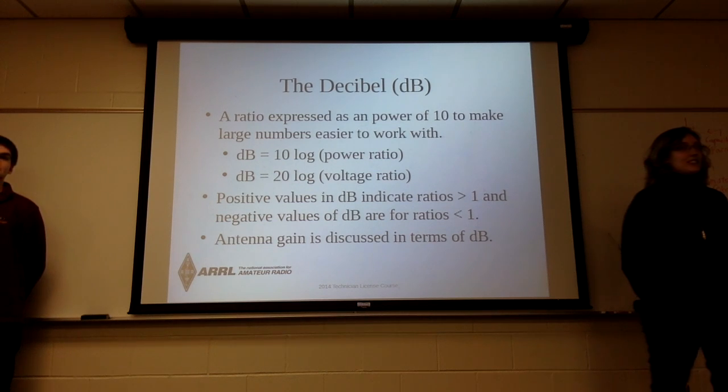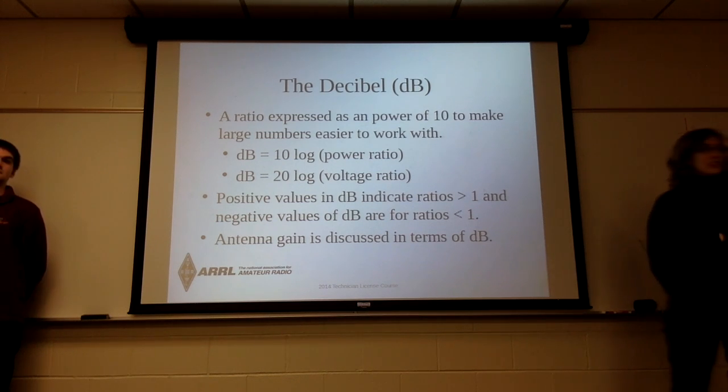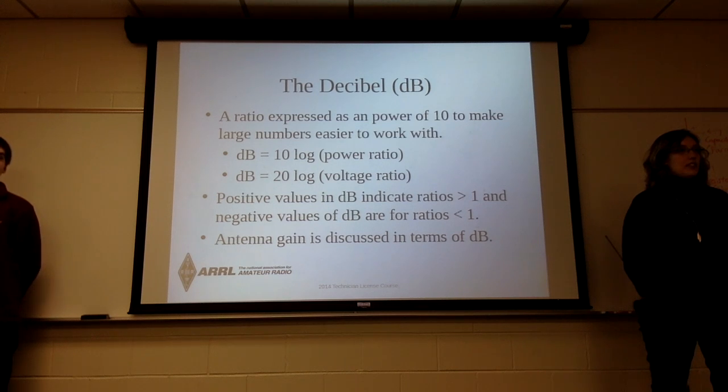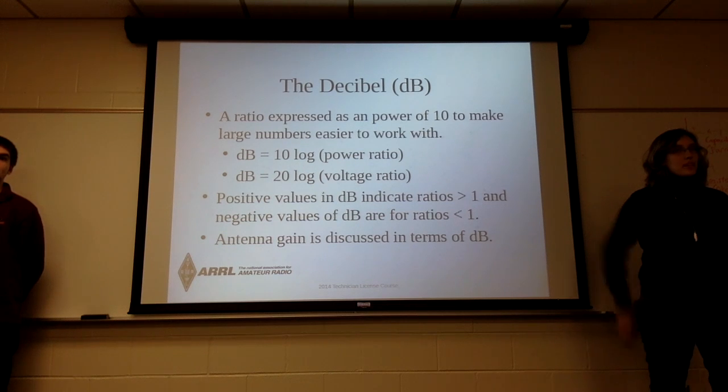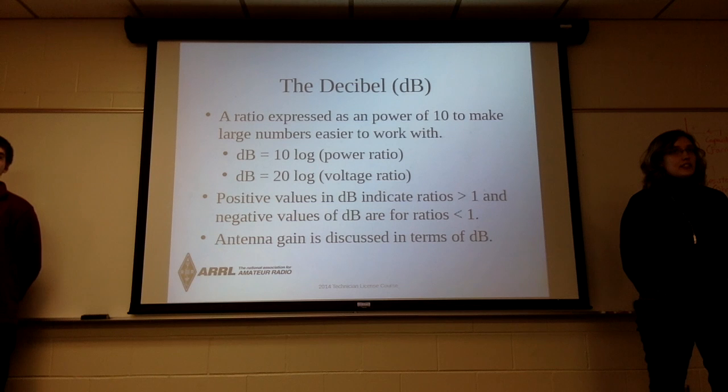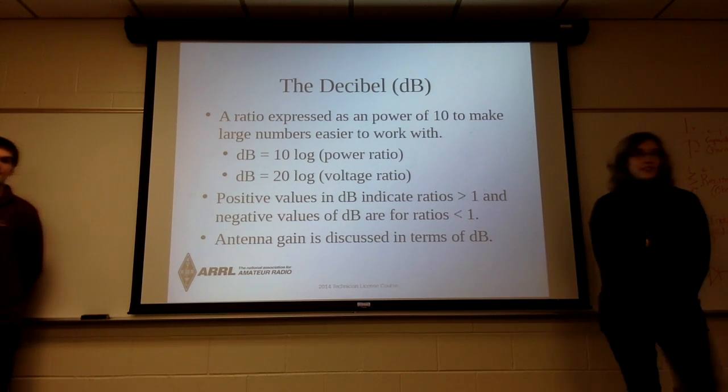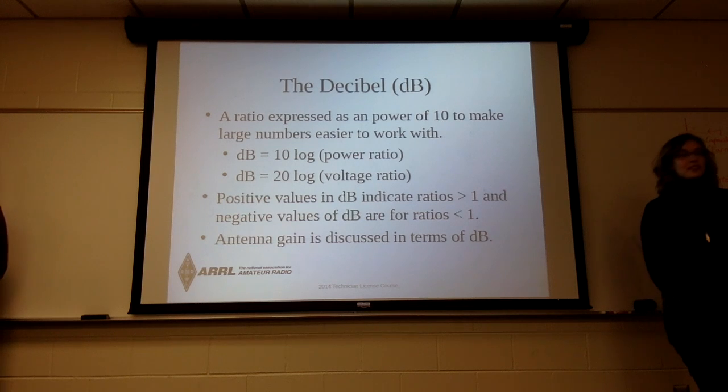Okay. Typically, mobile stations like me use vertical polarization. The repeater uses vertical polarization so it hears me better and I can hear it better. Point to point, if you notice the antenna on the top of Broom Hall on the tower, it's horizontally polarized. Fixed stations tend to use horizontal polarization, even on 2 meters, when not talking to a mobile station.